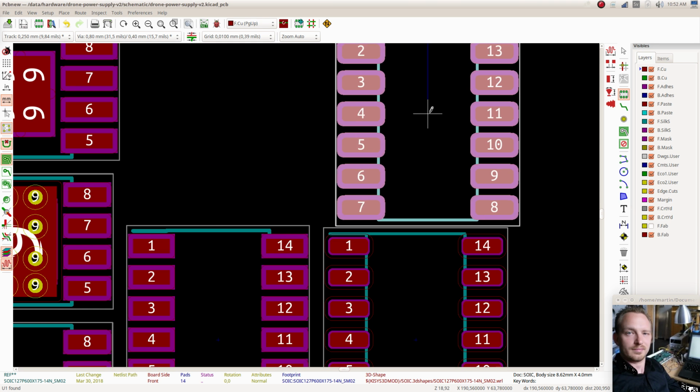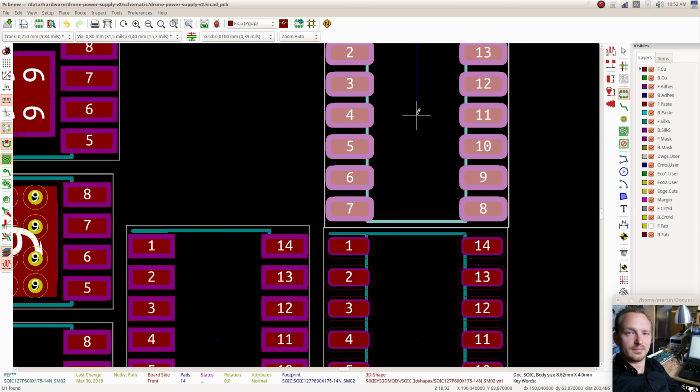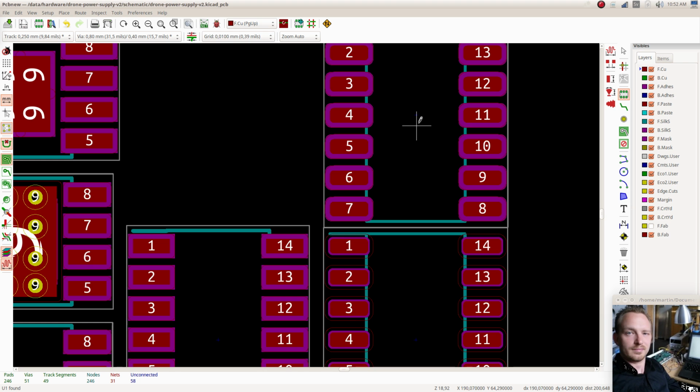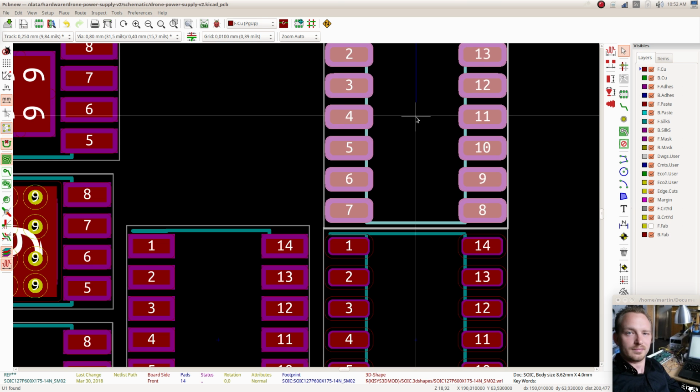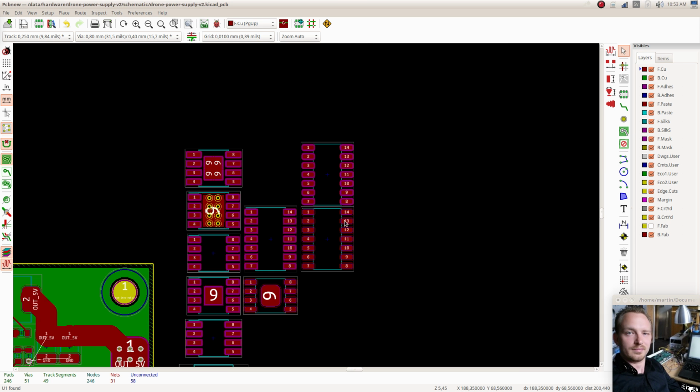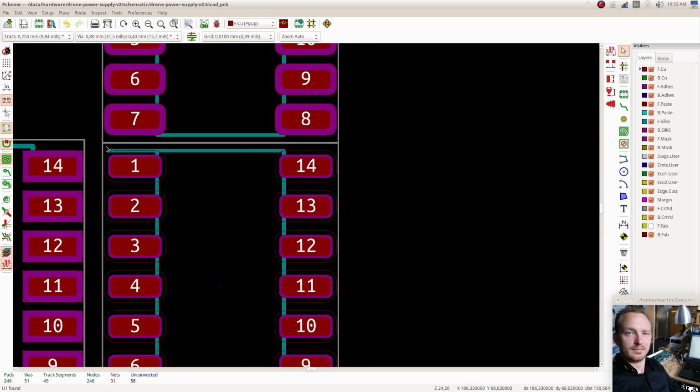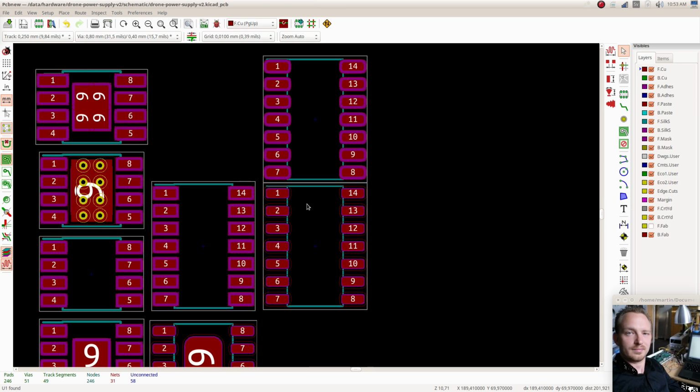And then you have this solder mask 02. And when it comes to alignment, I can align things really nicely using this courtyard around the package. But let's say I want another package, using the board density setting that is the low density one. With KiCad I wouldn't be able to do that. I would have to copy this footprint and then modify it manually to account for the board density. I don't want to do that.